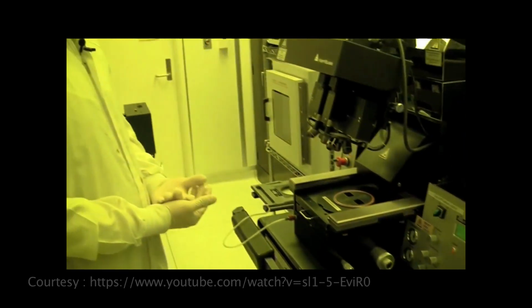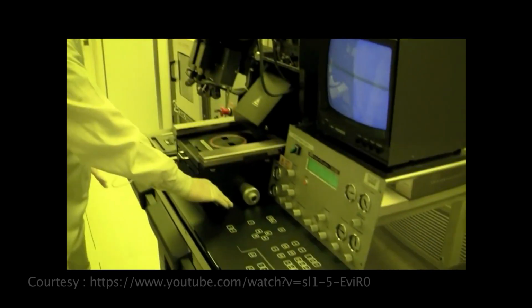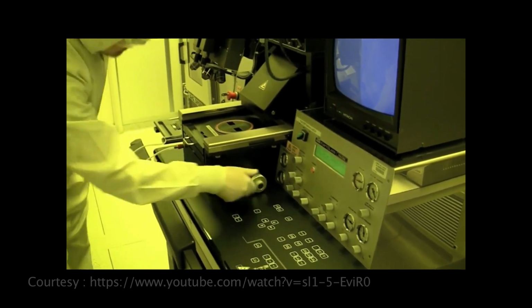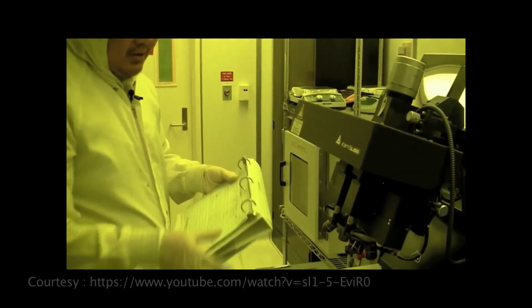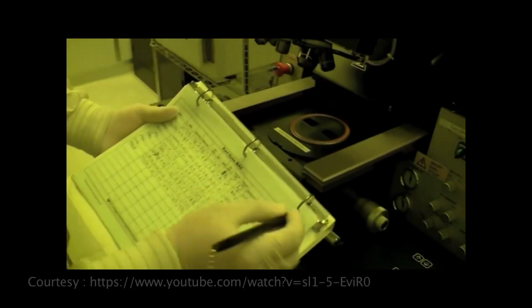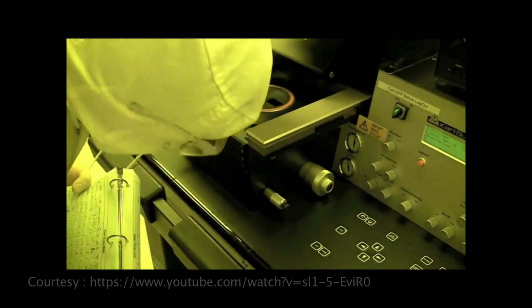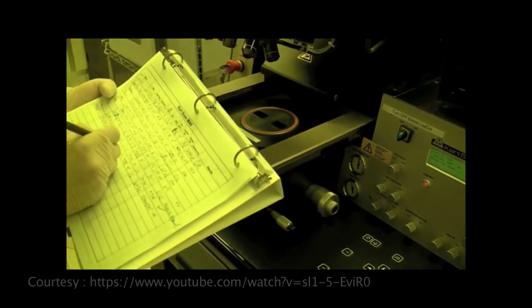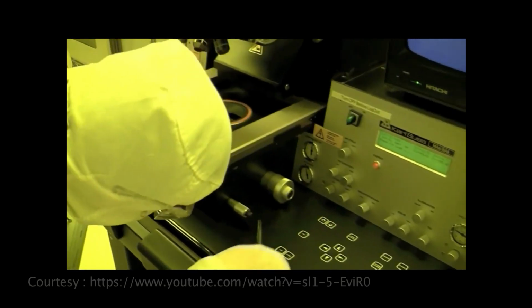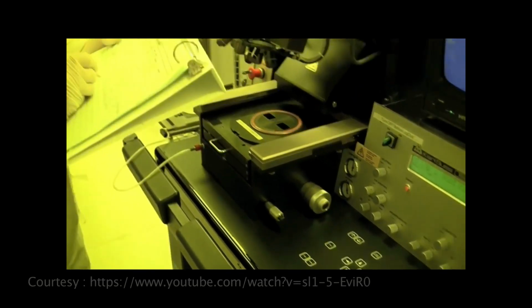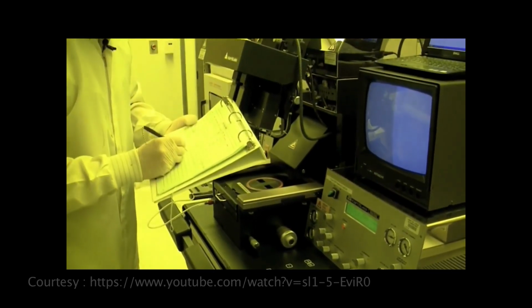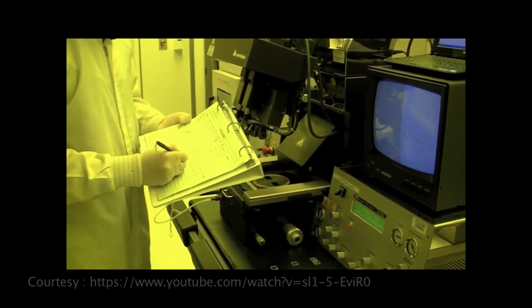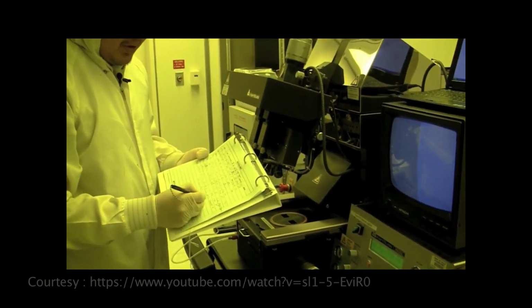So now we're ready to turn the system off. So we want to make sure everything's in the standby position that you started the machine with. And then before you turn it off, you want to make sure you write in the logbook the different parameters. So the compressed air is about 4.9. The nitrogen is about 1.65. The vacuum is about negative 0.86. We used a 4-inch wafer with silicon, and we did 25-second exposure.